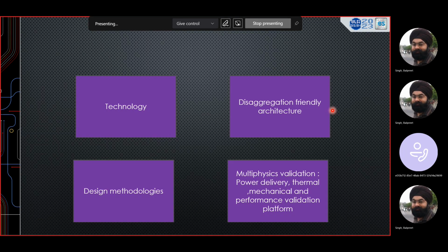So when you talk about bringing up the new technology, it basically means how seamlessly you can produce close to 100% yield in terms of the microbumps. Think about this. Even today, with the large C4 bumps, which are typically about 80 to 100 micron in diameter, you still see yield problems if you try to make a big, let's say 500 millimeter square die package. Now, when you try to make the same smaller structure, how do you predictably build that?